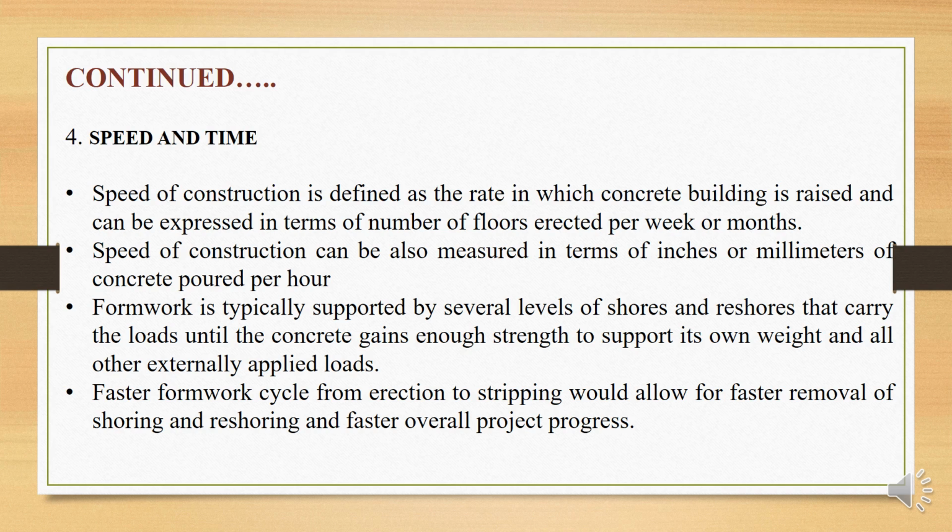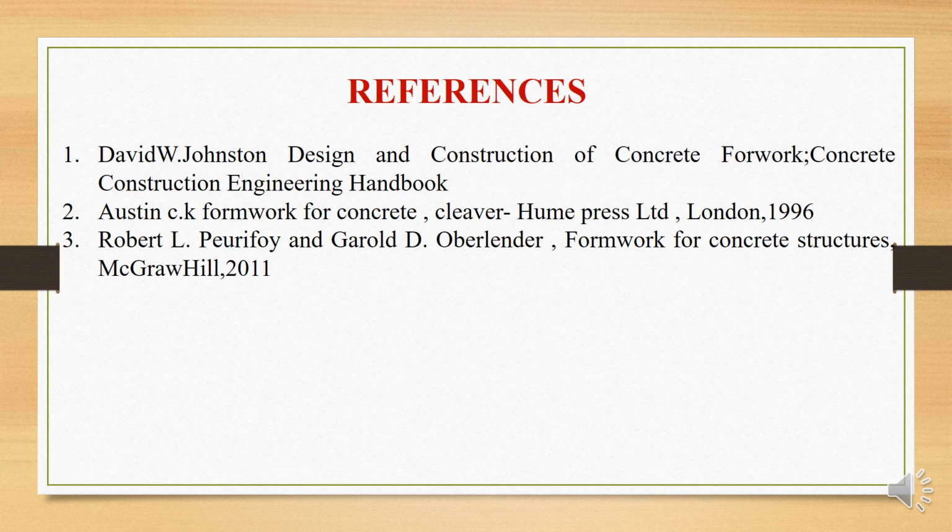As a result, several floors may be blocked, preventing the progress of any other construction activity. A faster formwork cycle from erection to stripping would allow for faster removal of shoring and reshoring and faster overall project progress. These are the references I referred.